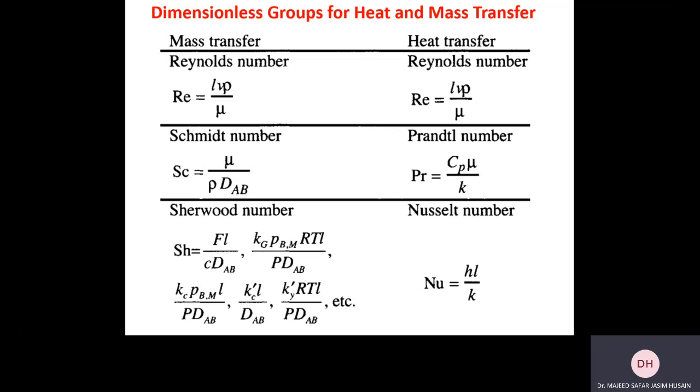So Reynolds equals rho u d over viscosity. And instead of d, we are putting L, which means the characteristic length. For a tube, for example, you are going to use the diameter. However, you also have to consider the shape of that pipe, etc. So rho u d over viscosity, let's agree on that.